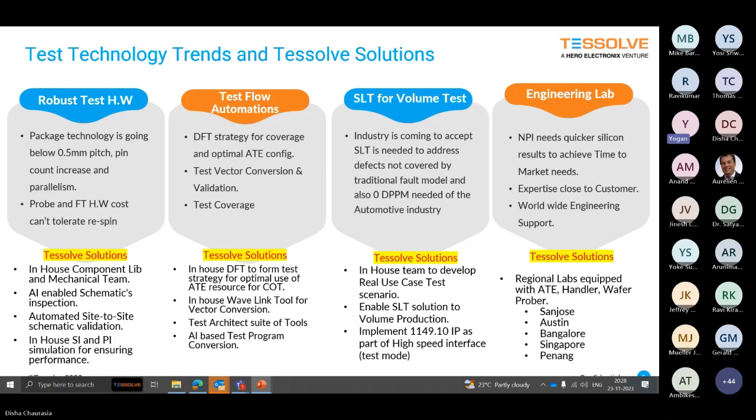Designing such hardware also needs to keep in mind that you can design it, but can it eventually be manufactured? Looking at the testability for the volume requirement, there are minimum thicknesses you need to maintain, and the number of layers could exceed 40 layers. And looking at the aspect ratio of the pitch, you may be limited to a couple of vendors who could do the fab. So designing a solution based on the requirement, and eventually materializing the design into hardware that can be manufactured, is a key thing.